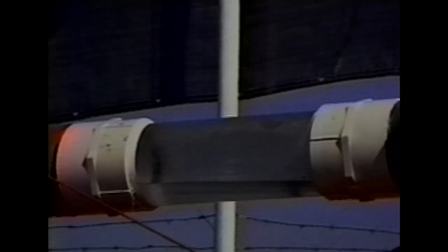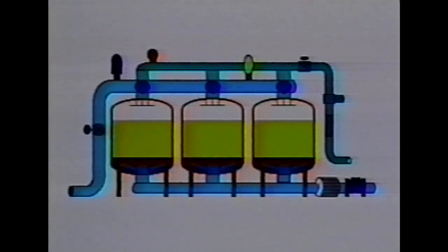Another is a section of clear plastic tube, which allows the operator to see if the backflush water is dirty or clean. This tube should be kept covered to protect it from sunlight damage, except during backflushing.